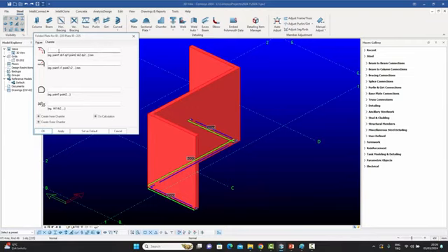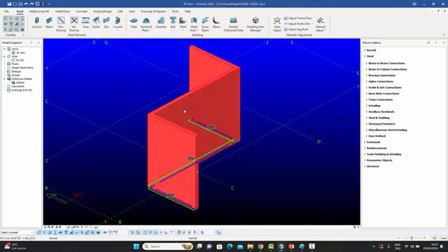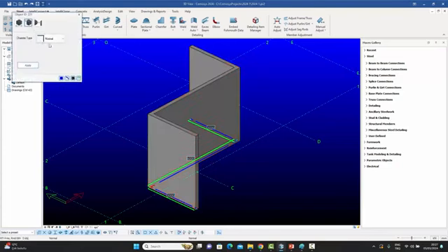We would need to enter 2, which meant the second point, and then give the chamfer parameters something like this, for example, and then we would get our desired chamfer. And now in this version, we have just given direct on-screen editing. So you see the handles appear now, which previously did not. And you can just go and select that chamfer for the second point and just say that I want to give this a chamfer, this type, and you just give those parameters. So you don't need to remember which point was which, which made it a bit difficult. You can just go like that.